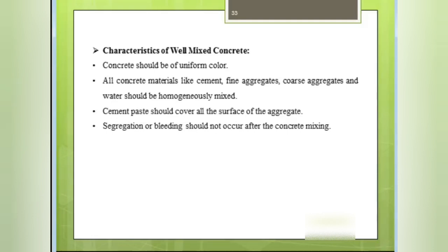And if PSC, that is slag cement, or red oxide cement we are using, then its color should be quite brownish. But it should be uniform throughout, not one part of the mix in one color and another part in a different, lighter color.